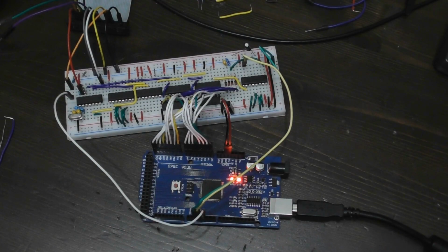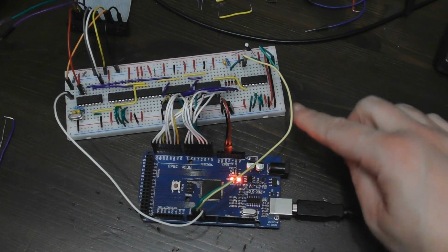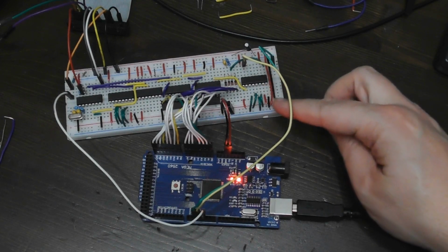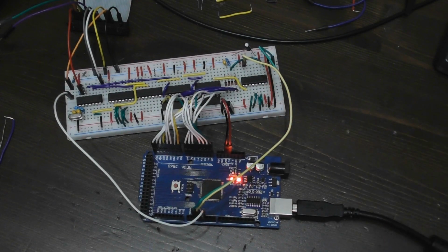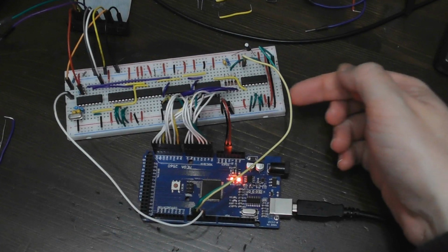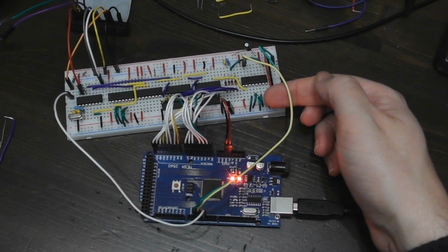So here's the Arduino all hooked up to the circuit. One mistake I made earlier that was particularly significant was the initialization value for this counter over here, which I had set to 6. The reason I set it to 6 was because I wanted to skip 6 bits before telling the Arduino that the byte was ready when it was reading an address mark. However, what I overlooked was that this is an up counter, not a down counter. So if I wanted to give a signal after 6 bits, I need to set it to 16 minus 6, which is 10, which is what it's set to now, rather than 6. So I've corrected that here. That's the only real change from the other circuit that you already saw.